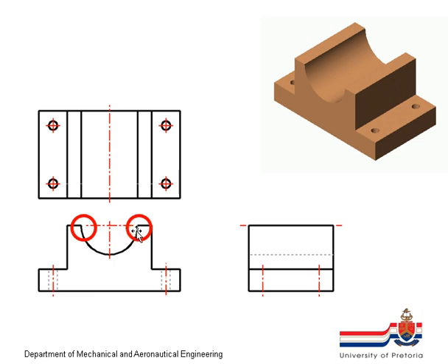The center line doesn't touch the edges over there, the center line for the big arc, and the reason for that is if we touched over there it would look like a continuation of this outside line. So to avoid the confusion we leave a gap over there and over there. This vertical one can go over the circle's radius because it's not in line with a solid line.